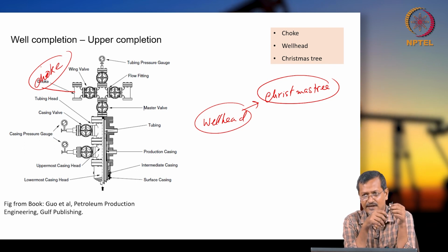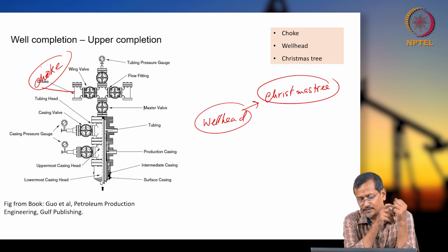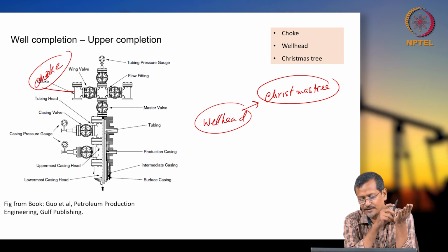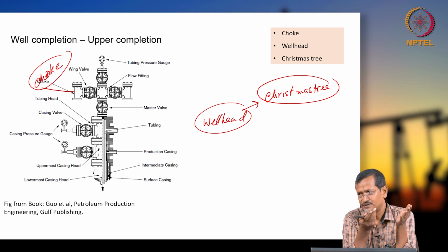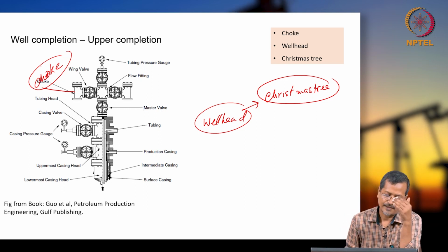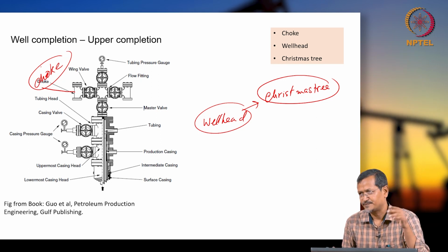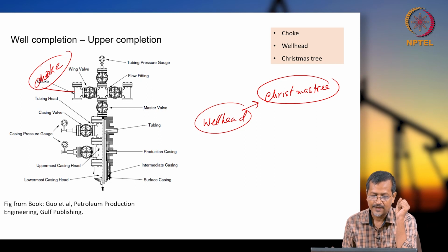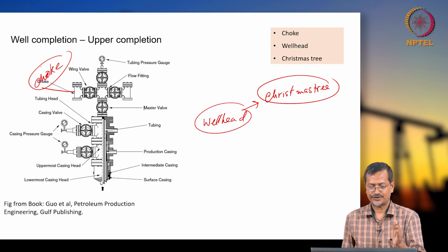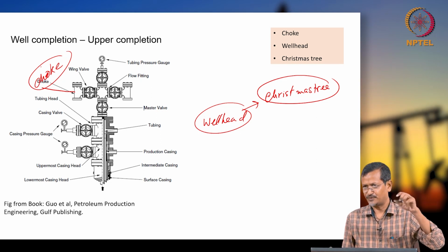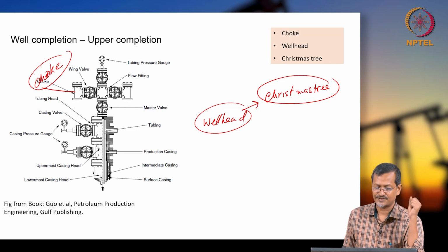In that case you have to select material properly, so that it will not affect your systems so much. Sand can be deposited in your separator system and pipeline system, and erosion will occur. And suddenly you change your production rate because of choke manipulation, or you want more production tomorrow because the oil price is rising.